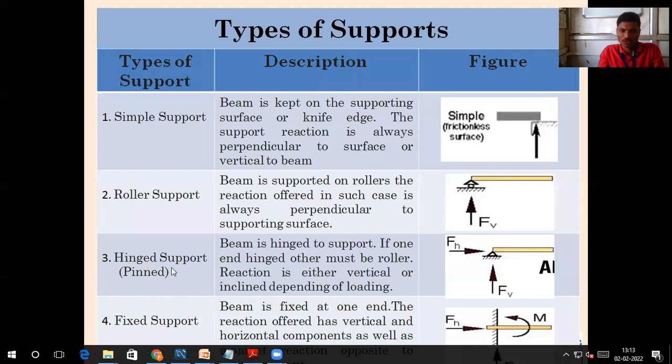Do you remember the hinged support example? Anybody remembering one of the examples I have given during explanation? An object can rotate, but it can't move. More precisely, I will say hinged support. The object can rotate, maybe along its axis or one of the edges, but it can't move. You cannot move it horizontally, nor vertically. That's why reactions are generating.